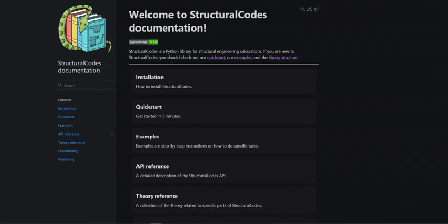What do you mean by constitutive laws? So that would be a relation between stresses and strains for a material. So for example, a linear elastic one, or a parabola rectangular one, or an elastic plastic one. So for everything tied to stress, strains, or deformation of a cross section, for example. Yeah, you got it.